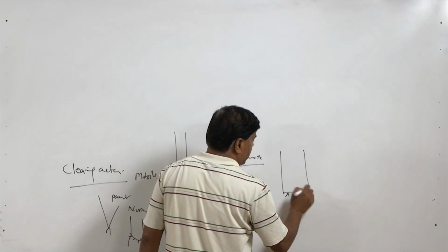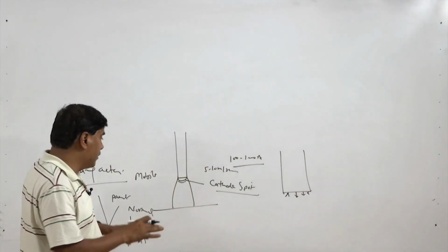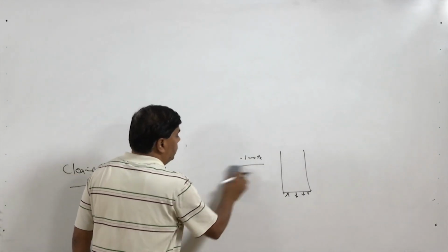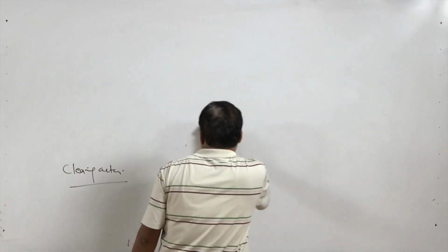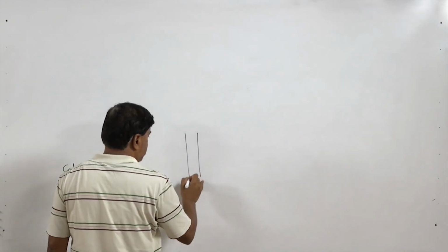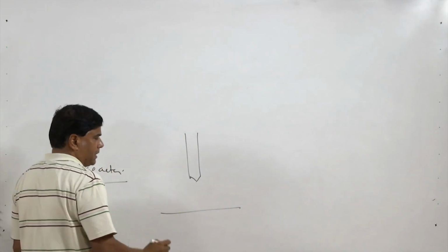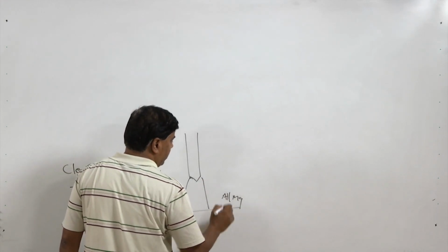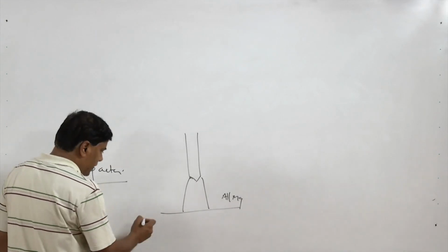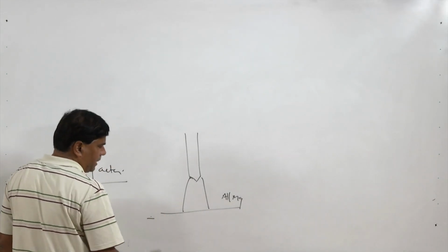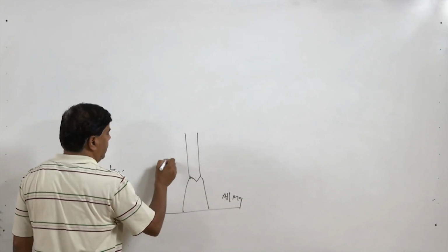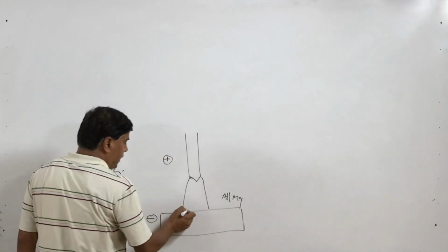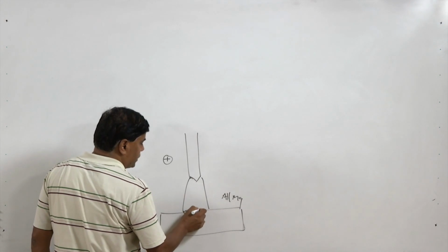In this case the location of the cathode spot keeps on changing. This concept is exploited from the cleaning action point of view. If the workpiece is the cathode and a mobile cathode spot is formed, like say with a tungsten electrode or any other process electrode, for example when aluminum or magnesium are welded using the GTAW process, making the workpiece negative and the electrode positive, then our workpiece is expected to emit the electrons, and the mobile cathode spot is formed at the surface of the workpiece.